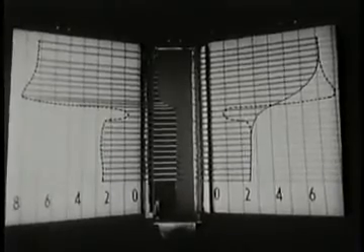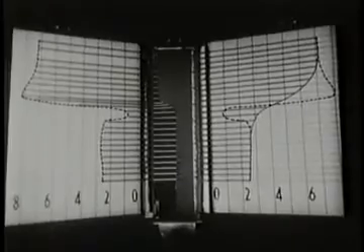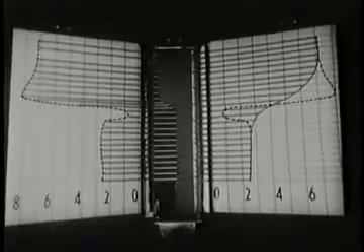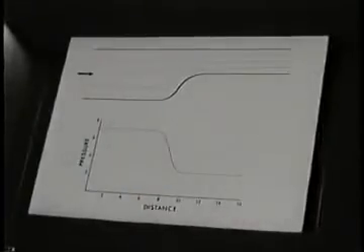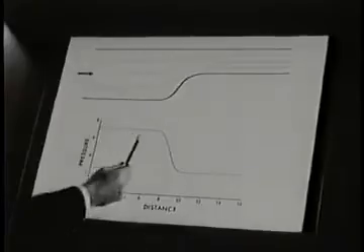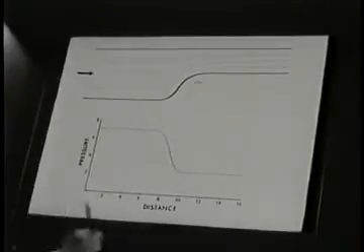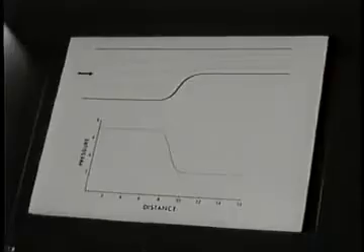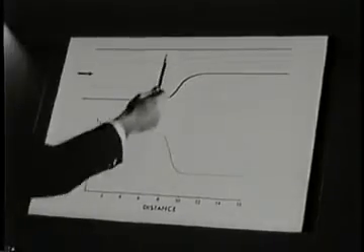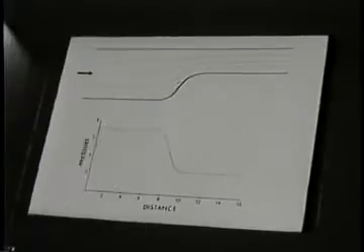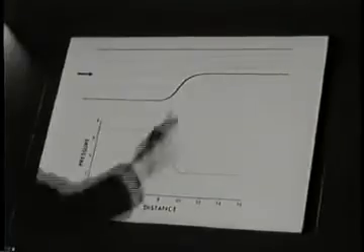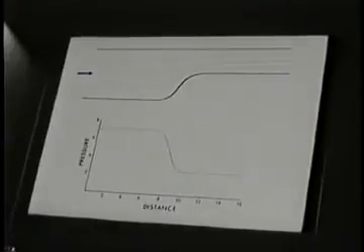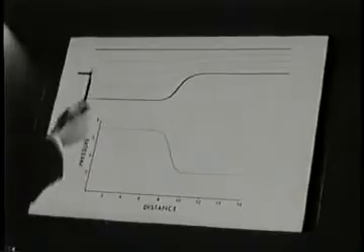This curve of pressure versus distance shows the average streamwise pressure variation associated with the one-dimensional average velocity at each cross-section. Far upstream and far downstream, where the streamlines have no curvature, the pressure will be uniform over the two cross-sections. From the shape of the channel, we may expect that the streamlines will be of this general shape: concave up in this region, concave down in this region.